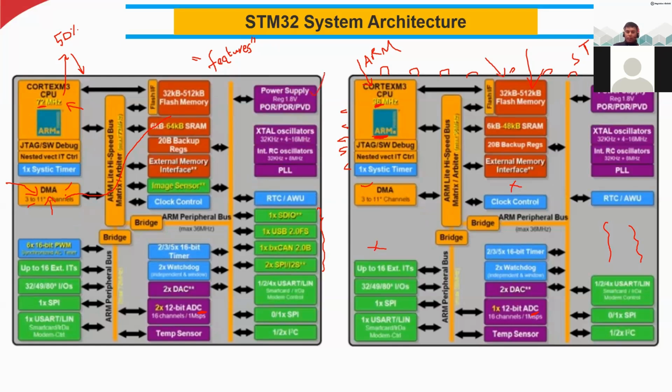And here you can see the power supply. That is what we give externally, and then the power supply is given to other units inside this microcontroller to drive them. And we have the oscillators to generate the system clock. There are different types of oscillators that can be used inside. And we have the phase-locked loop, that is a PLL. These are all to generate the clock. The clock signals synchronize the operations between different blocks and control everything, including the time delay.